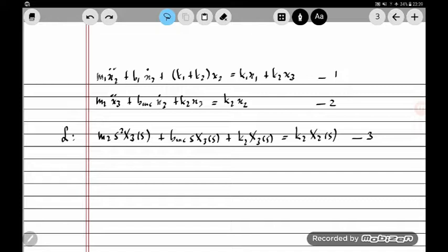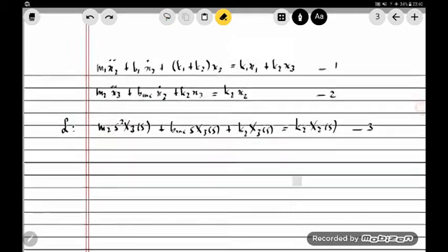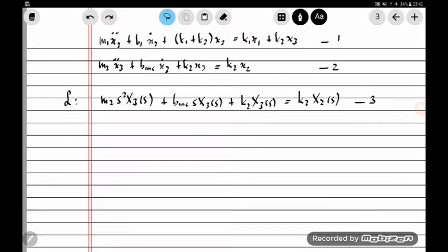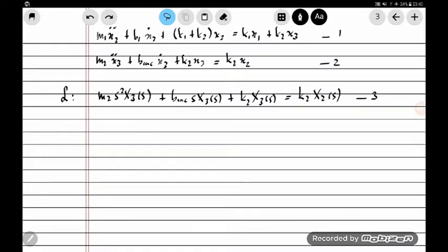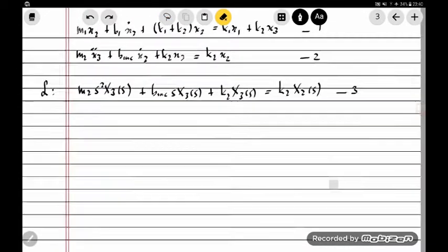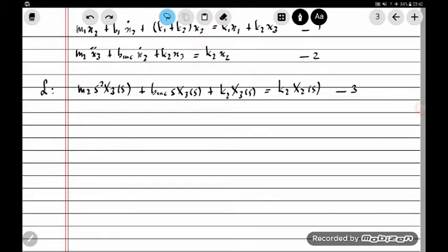Okay, so keeping this in mind, I will start off like this. I know the highest order of the derivative in my model, in this case equation 2, is 2. So I will use 2 integrator blocks in series like this. I need to bear my space in mind because this is going to get to be a detailed transfer function block diagram.